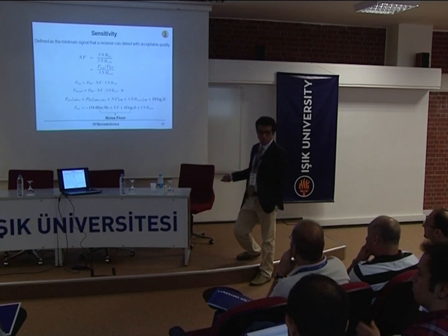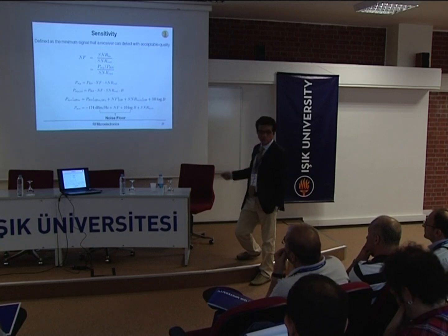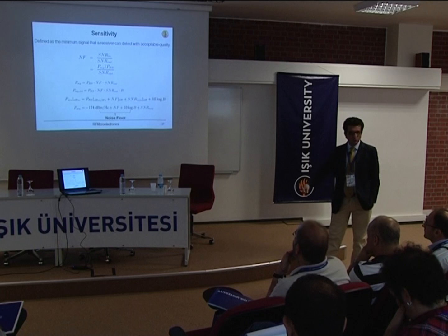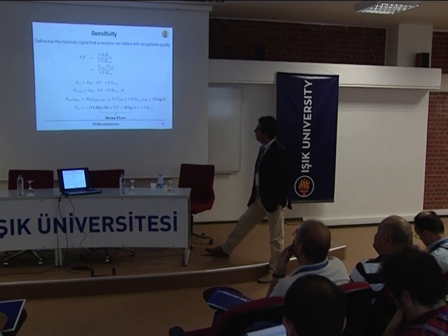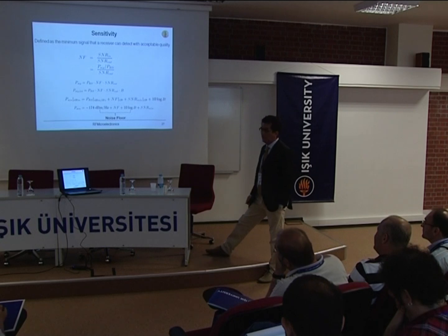So we know the bandwidth, depending on the application. We know, given the modulation, what is the minimum signal-to-noise ratio to go into the baseband processor. And so what we need to do is reduce the noise figure as much as we can. And this is something you do as an analog designer, and this is really your job.